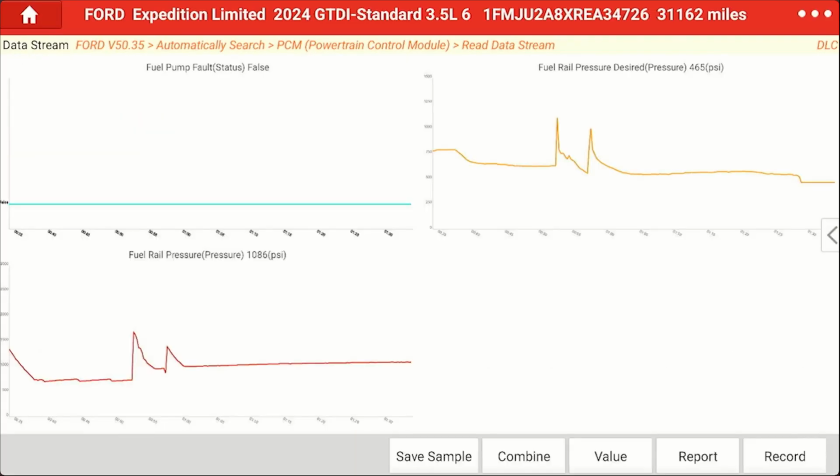Now, if you notice, I've got the low pressure fuel here and I've got the high pressure fuel. There are 2 different scales. One goes up to 600, one goes up to 3,000. Obviously, the one that goes to 3,000 is the high pressure. Notice that I'm going to accelerate. When I accelerate, notice what happens to the screen. The screen automatically changes its parameters so we can see both on the screen. So we're monitoring and graphing the low pressure fuel pump pressure and the high pressure.